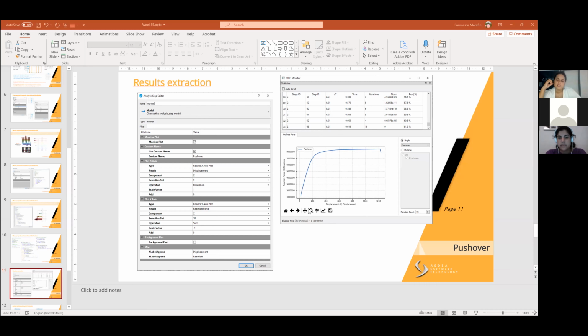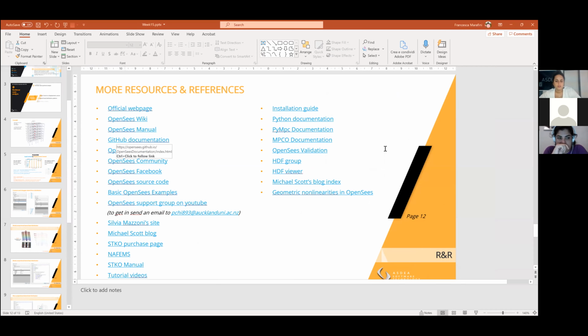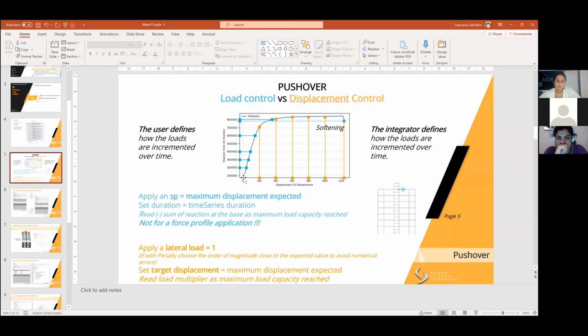Yeah, the point is, if you see what I showed before about the control, how does it work? Displacement control works so that displacement always increases. That's how it can capture things like this, because displacement can move up and down in terms of corresponding force, but anyway, displacement always increases.